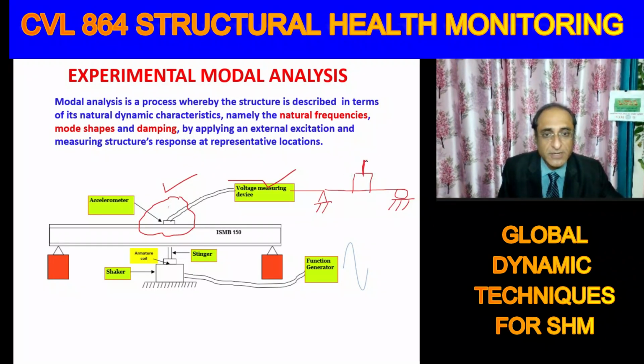The stringer we are not connecting to the structure directly, but what we are doing is installing a plate, and then connecting it to the structure by means of these springs. Now what is happening is that when the shaker's actuator is vibrating, it is exerting force on this plate.